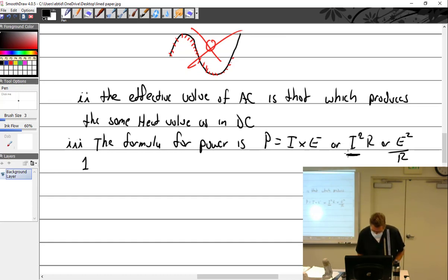Boy, I decided one day I was going to go into this and do the whole thing and show you how that happens, but we'll just skip down to this. Another way of saying this is all the instantaneous values of the sine wave are squared. The results are added together, divided by the number of results to get an average or a mean. Mean means average value. So the square root of this gives the effective voltage.